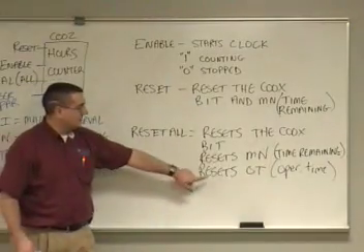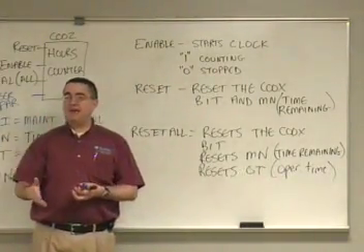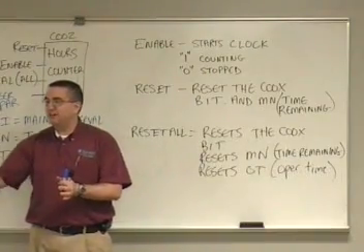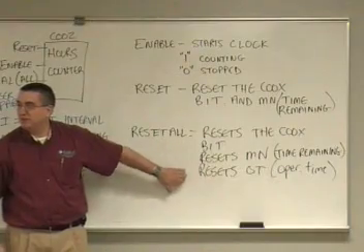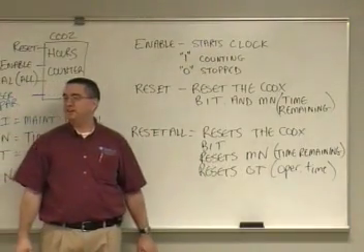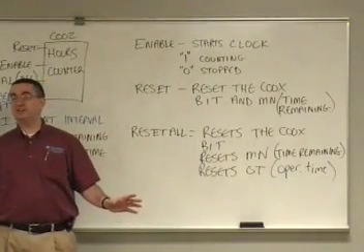But we're not going to reset OT, because it might be important to us to perform that maintenance every 3,000 hours, but maybe we want to never reset OT. Because what can we track then if we never reset OT? How many hours total the machine ran? Yeah, the total machine runtime.